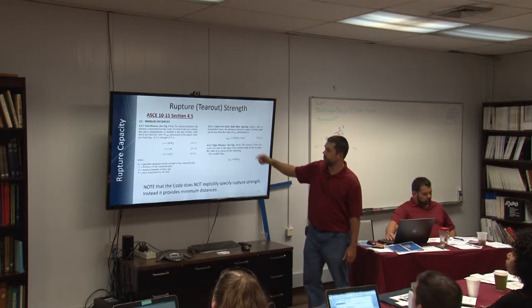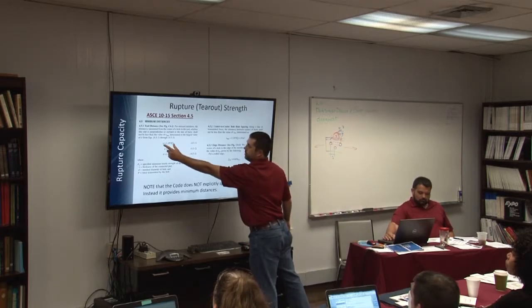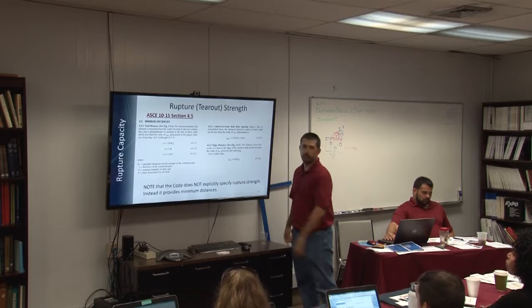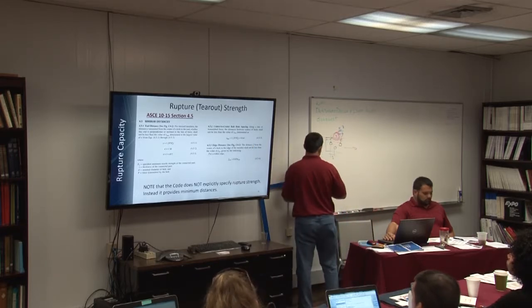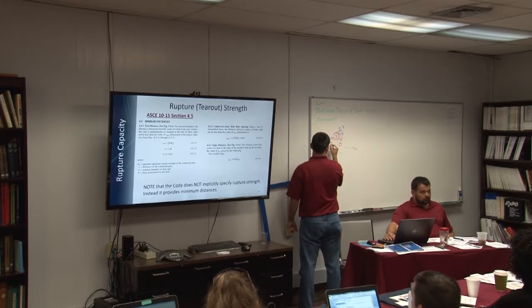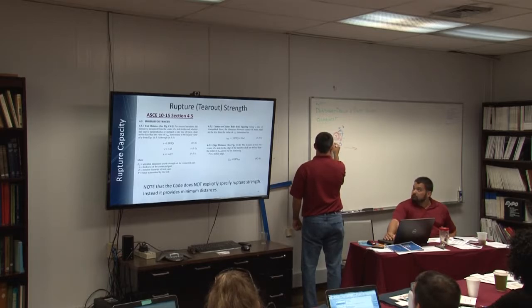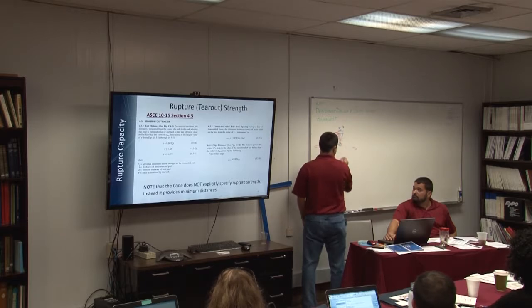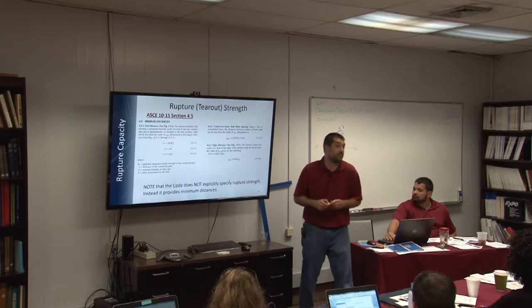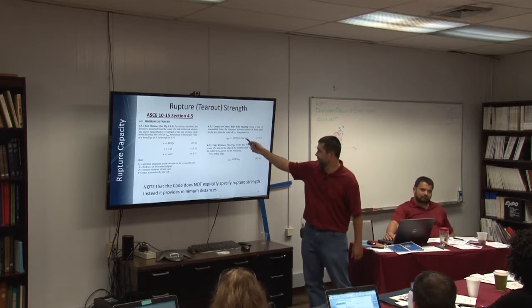Center to center hole spacing. It's essentially this equation plus half of a bolt diameter. So the idea is that if my end distance here is E to the center, then I want to provide this at minimum the same distance to the edge of this hole plus 0.6 bolt diameters gets me roughly to the center of the hole, right? So that's where this comes from.